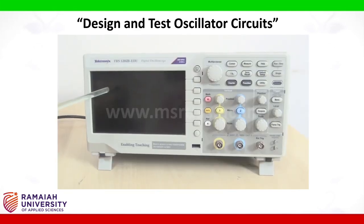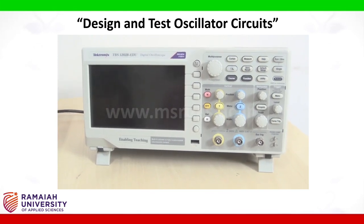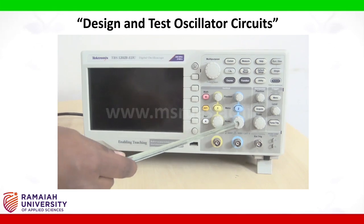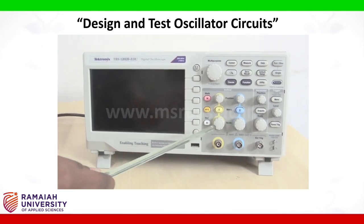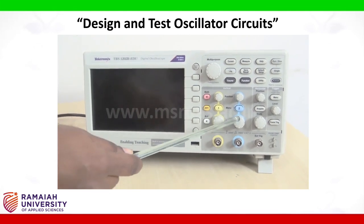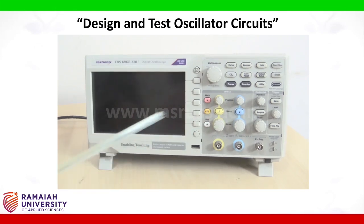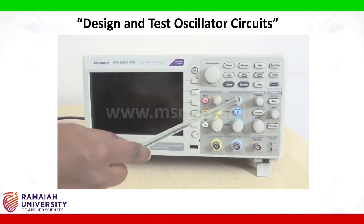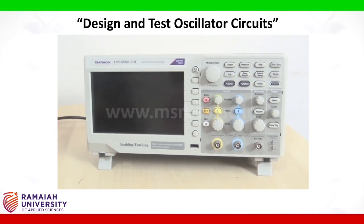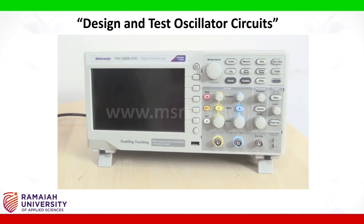Oscilloscope. This is CRO, digital oscilloscope. This is used to check the waveforms from any circuit. We have two channels. Each channel can show voltage as a function of time. The voltage scale can be adjusted using these buttons. This is used for time adjustment. These two control the position of the vertical movement of the waveform. This controls the horizontal movement of the waveform.